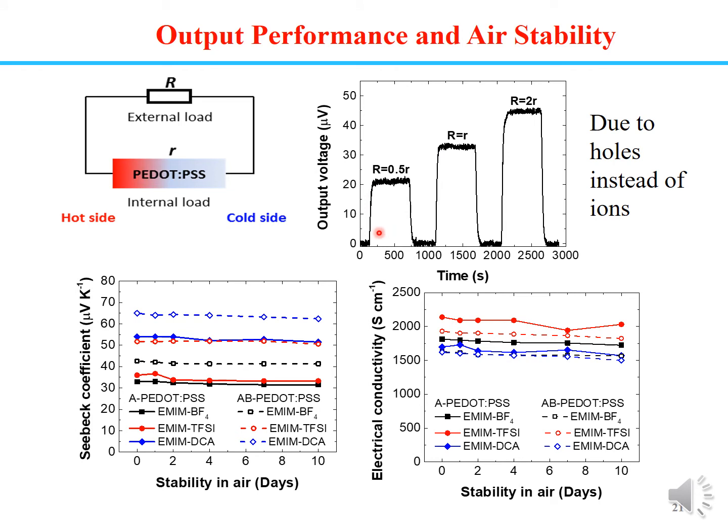We further demonstrate that the Seebeck coefficient is due to the holes instead of ions. We connect the PEDOT:PSS with a layer of ionogel to an external load. Then we found that the output voltage is flat with time. So this indicates it's not because of ions.